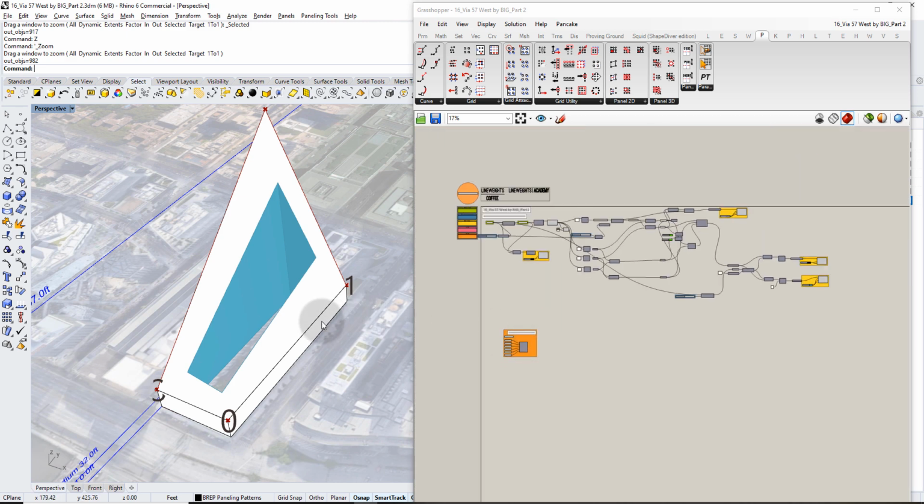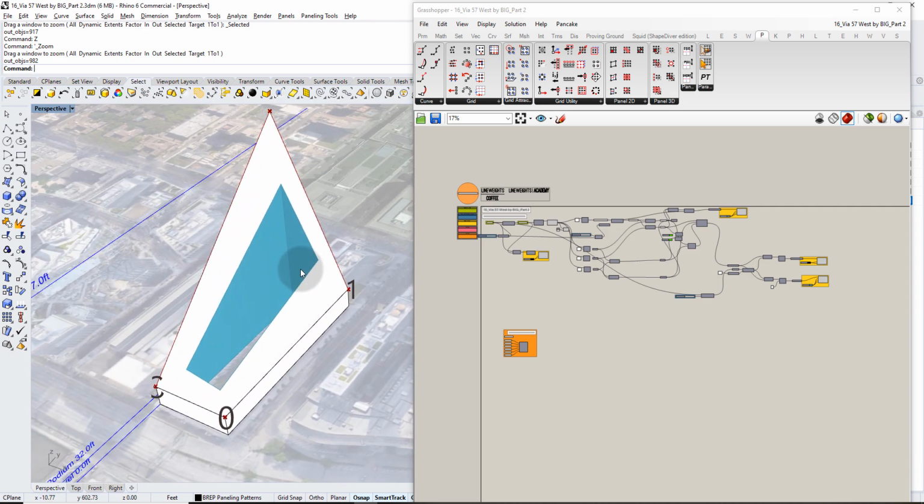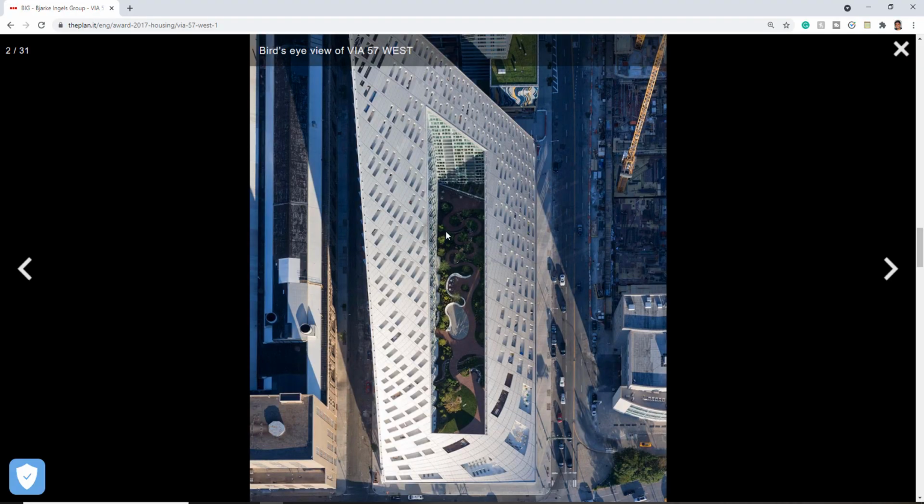First, let me show you how to actually create those divisions. There's a couple of ways. Notice that they usually go in 2 directions, right? So you're looking at a grid. Even a rectangular grid usually has columns and rows, things going up and down and things going left and right. So the first thing is to identify what's going up and down, and what's going left and right. The up and down are these lines right here going across the building, that start to go on the diagonal, and then the left and right are these balcony lines. So we're going to create both of those separately and then join them to create a grid and then populate that grid. That's how we're going to approach this project.